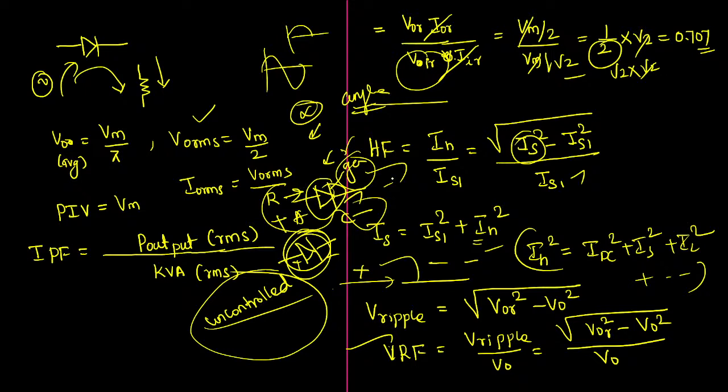So now in the case of thyristor, we have to decide. First we have to inject the positive voltage across the anode and negative voltage across the cathode. Next, the turn on process of the SCR depends on the gate, at which time we are going to inject this gate current. That time will be defined in terms of angle. That angle is simply called the firing angle. Like when we take a gun and fire it, similarly we fire the SCR: to turn it on, we inject the gate current. The angle at which we inject is the fired angle, that is called the firing angle.